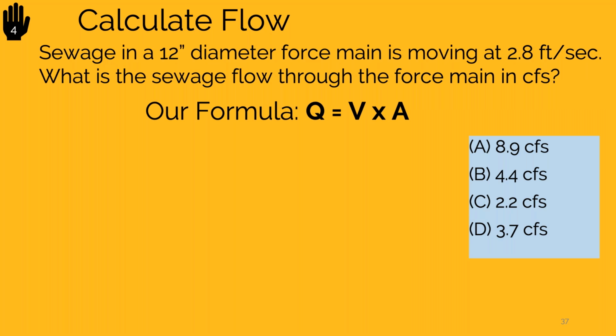And again, you're going to have to do a conversion here, because I've given you the diameter in inches and the velocity in feet. So just to give you a hint, you want to convert that diameter from inches into feet before you start doing your flow equation.